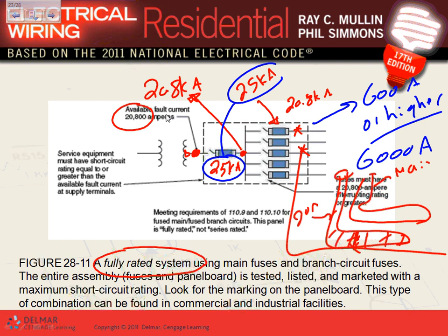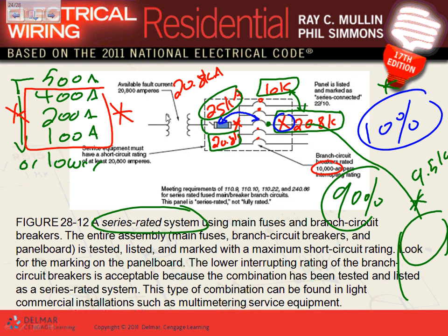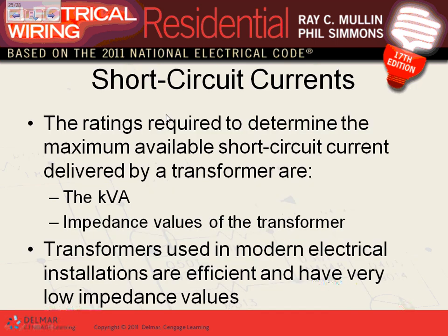If that one freezes and does not do anything, then the second one is where we do coordination. So overcurrent coordination for a series rated panel, guys, is not as good as for a fully rated panel. Any question? That's what series rated is. Next quarter, we have an expert from Cooper Bussmann who comes and shows a lot more details about this. Just remember that.